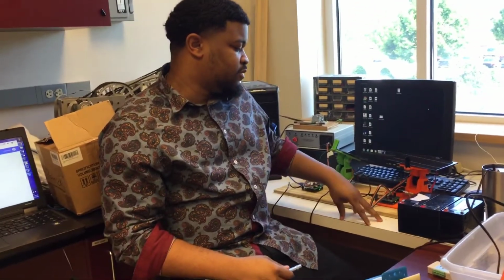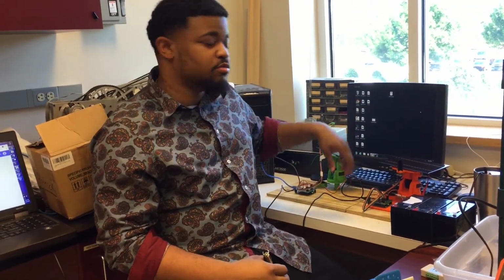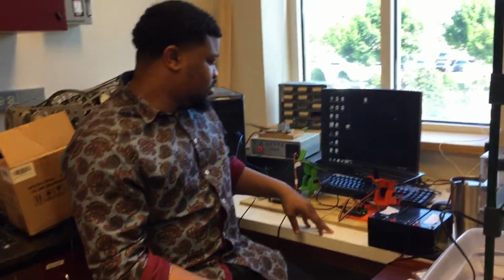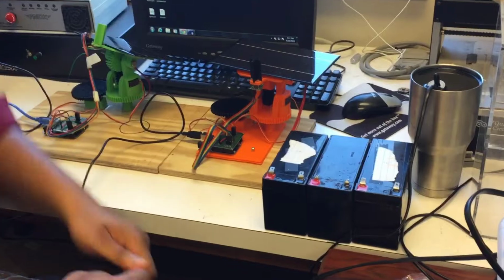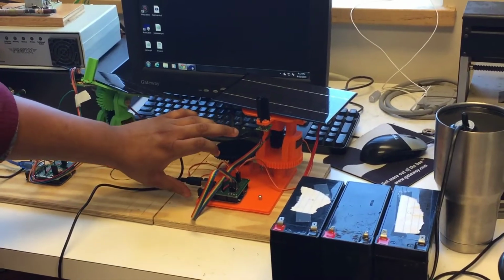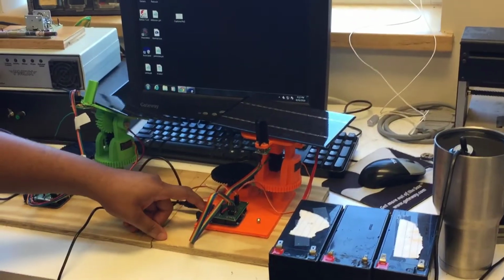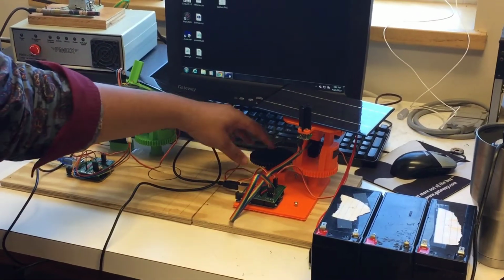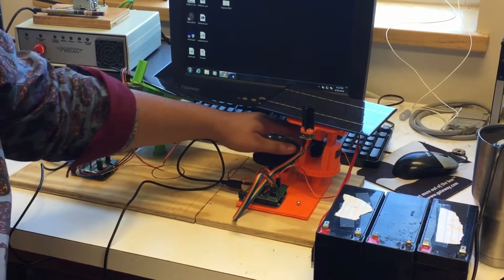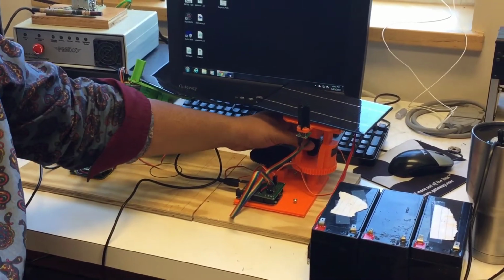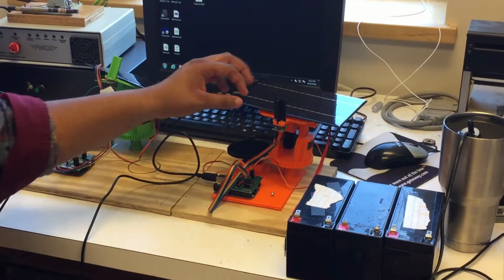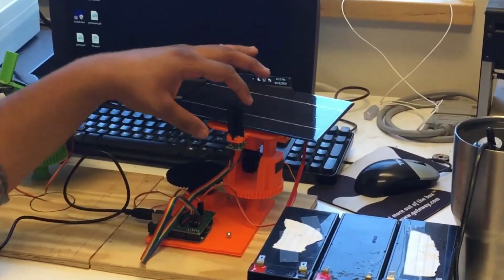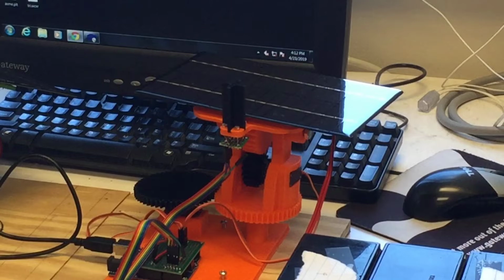Hello, my name is Aaron Warren, and what I have basically focused on was developing the solar tracker system. And these are 2 solar panels, both 18 volts apiece. This solar tracker design basically is run off of an Arduino Uno, and it has 2 micro servo motors, one for the horizontal axis and the other one for the vertical axis. And then we have 4 LDRs which react to the light sensitivity.